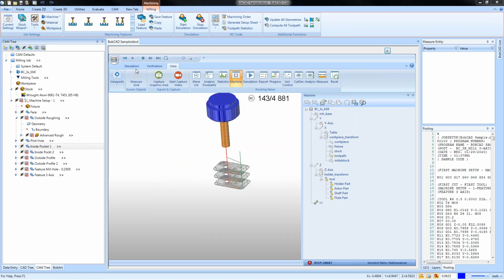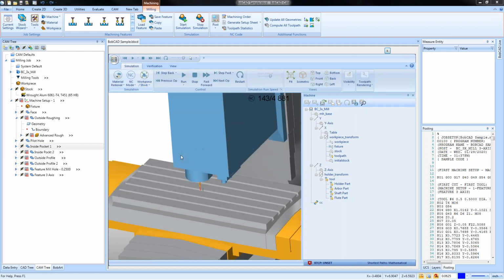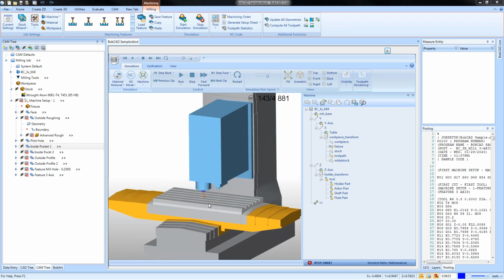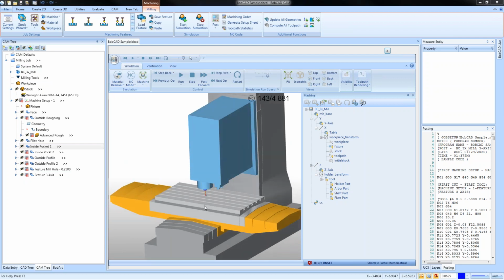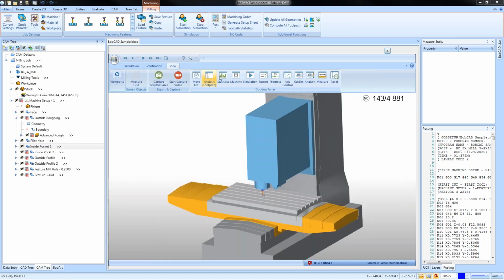If you're doing 4 or 5 axis machine building and you have machine simulation, you can click on the machine configuration within simulation, and it will give you feedback as far as direction and checking group, you know, what's being checked. This will give you visual feedback. Again, very, very helpful when you're trying to set directions and things like that.